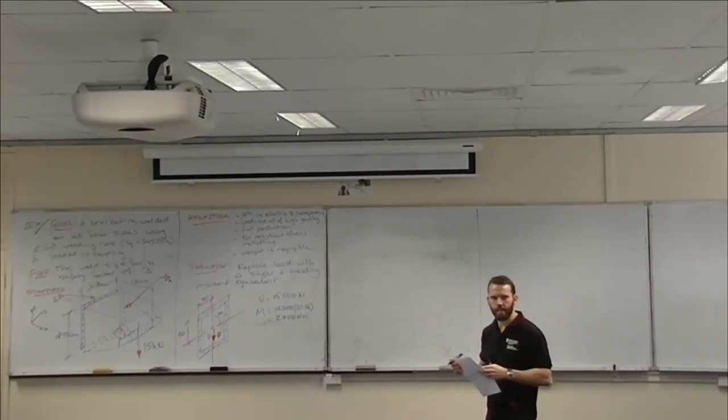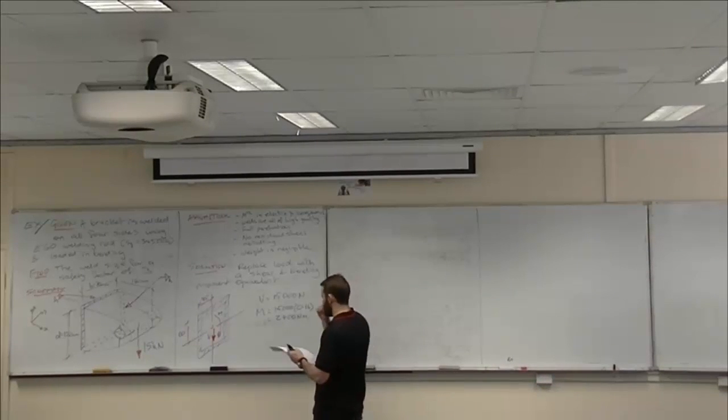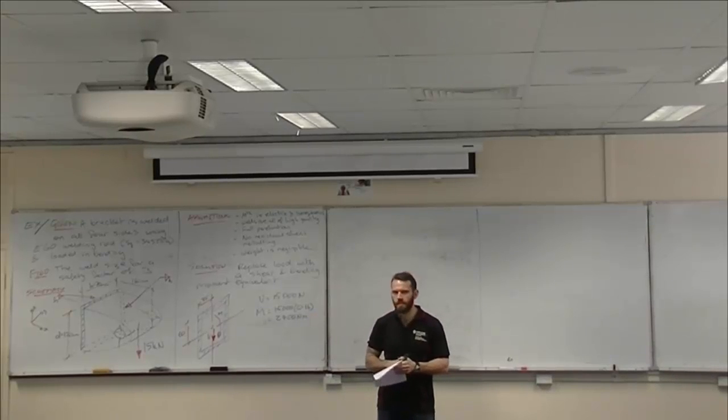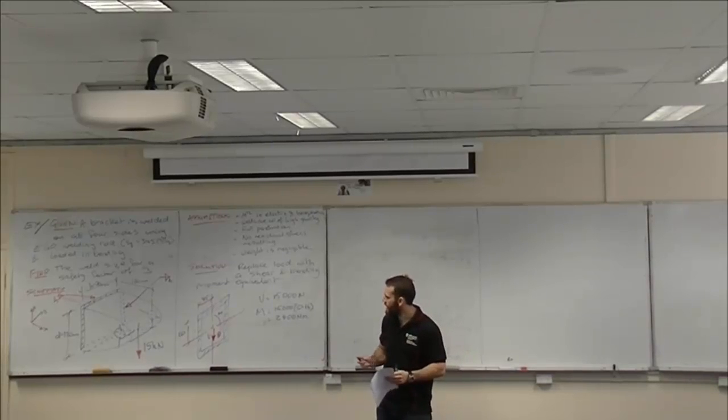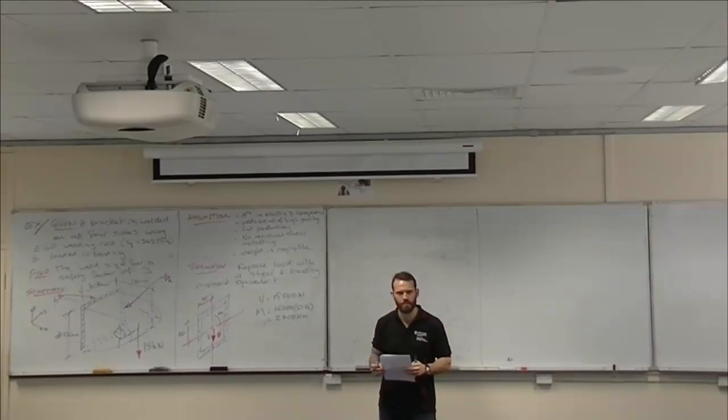Alright, everything we know about bending and transverse shear technically, where do you reckon the maximum bending stress is going to occur? Top, bottom, and because we know about bending, we know that it will be maximum all the way along the top and equal, and maximum all the way along the bottom, compressive and equal. Arbitrarily, I normally choose tension over compression, just because arrows out are easier to draw than arrows in, so choose whatever you want. But let's just analyse one point on the top edge of that weld as our candidate critical element.